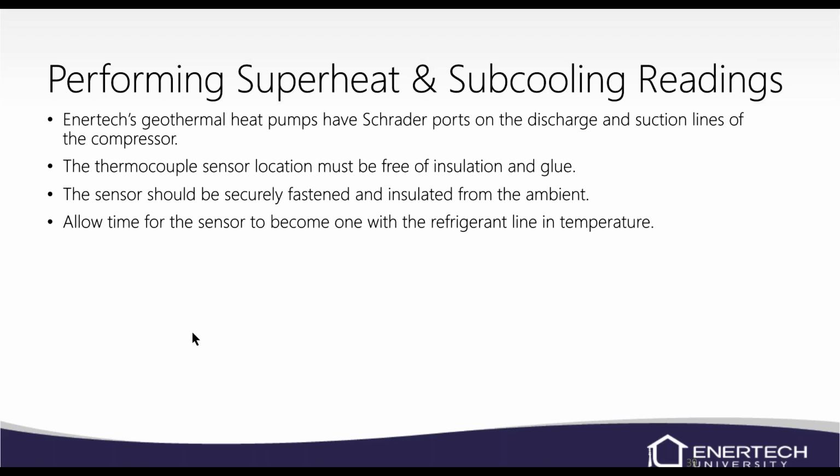Make sure your sensor location is free of any insulation or glue, and it should be securely fastened and insulated from the ambient temperature. I like to use a little clamp temperature probe, but you can use whatever you feel comfortable using. Make sure you allow a little bit of time for that sensor to read the correct temperature of that line.